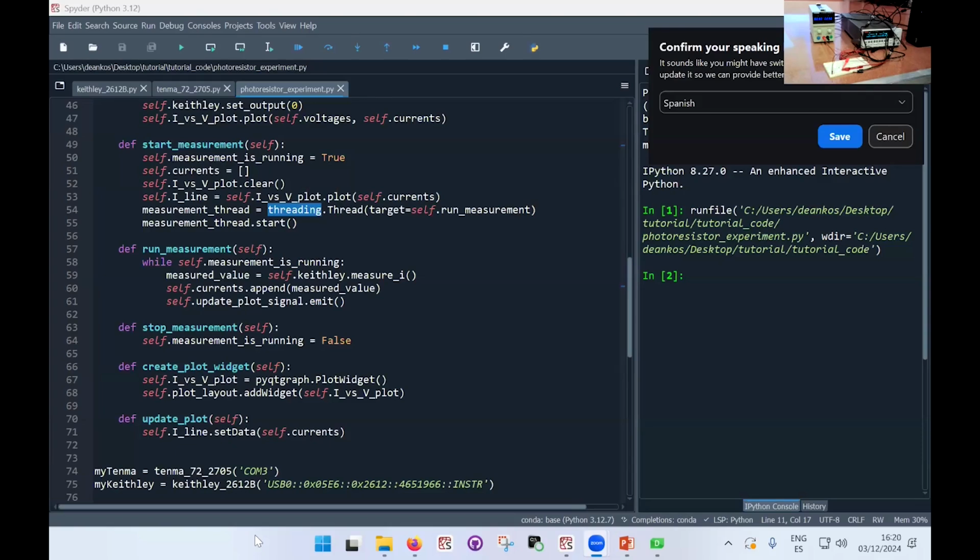You can do it all by Python and interact with the oscilloscope, and at a certain point say, oscilloscope, start acquiring now, but the timing of all this will be limited by the speed of the communication with the computer, which is, I would say, of the order of milliseconds. If you want to go faster than that, you'll need to pull out usually some kind of TTL signal. I don't know what that stands for. It's like a 5 volt or 3 volt signal that comes out of an instrument when it's ready to do something or when it's finished doing something. So that would probably be the way to do it.